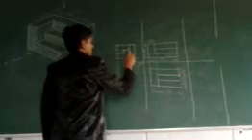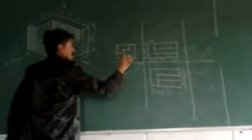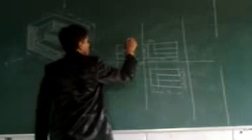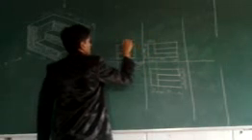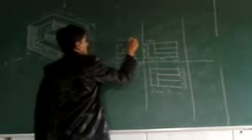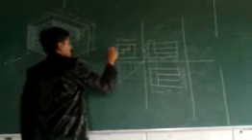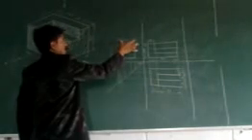See, this is the right side. So observe the hatching lines here. These are hatched areas, and this is also a hatched area. So that is this left area and the back left area. So this is about the right side. Observe the dimensions. So this is 30, 30, and 30, and these dimensions are 15, 15, and 20. Okay, so total height is 45, total width is 90, and total length is 108.